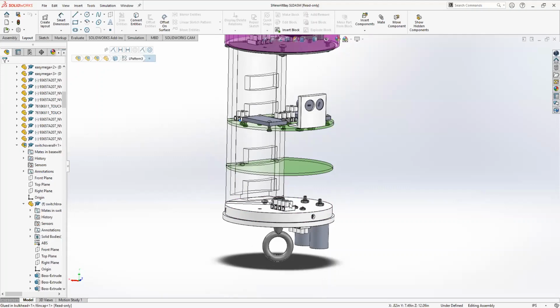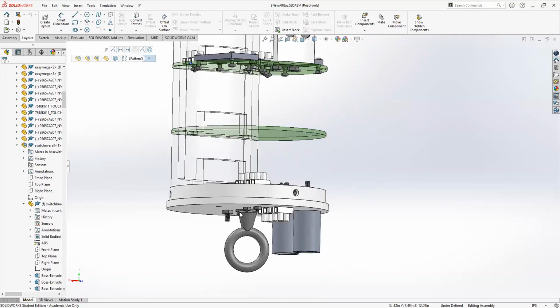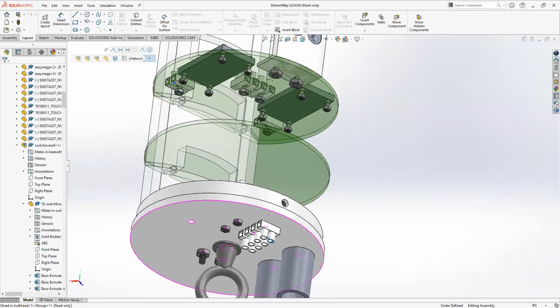explosions have quite a bit of pressure, so that will tell the altimeters wrong data about your apogee, and that could really also set off other explosions that you don't want to happen yet. So basically you want to make sure that your avionics bay is pressure proof. You could put some sort of epoxy or caulk or something.